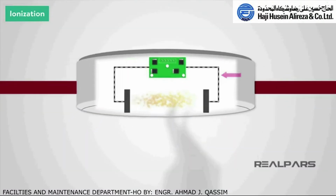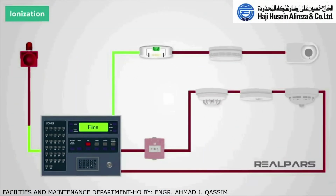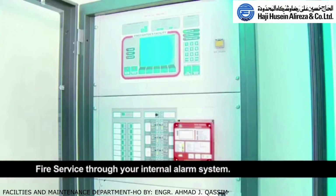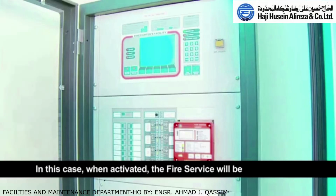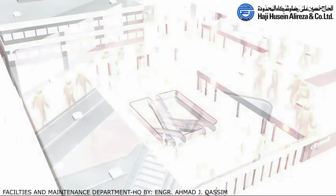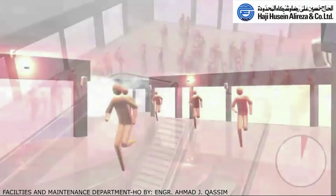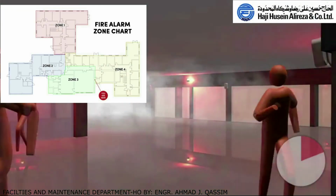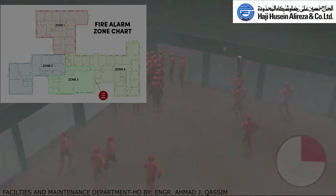Smoke detectors automatically send a signal to the fire panel in case smoke is detected, while break glass or manual call points need human intervention, just in case a fire is seen. By activation of any detector, a signal will be sent to the panel, thus setting the sounders to alarm or warn the occupants in the building. But take note, a false alarm may occur. It's better to check the panel for the place of detection to evaluate the situation.